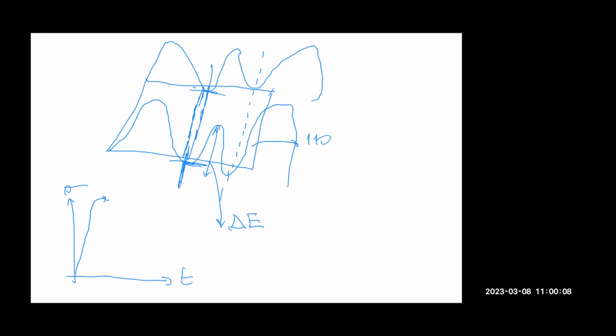But for FCC materials, you can activate the dislocation very easily. Very little elastic deformation, then plastic deformation, and boom, failure. They are not that strong. That is why we need to increase the strength of FCC materials without sacrificing ductility, and increase the ductility level of BCC material.